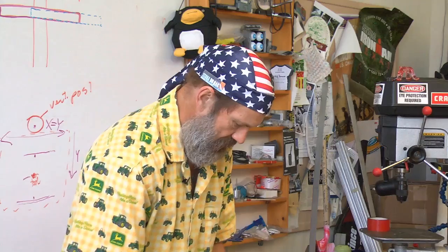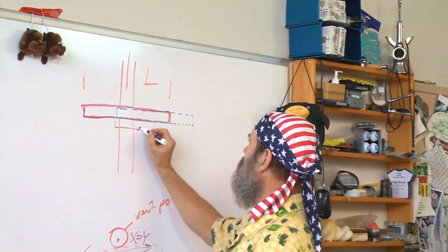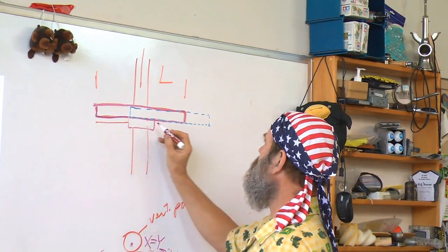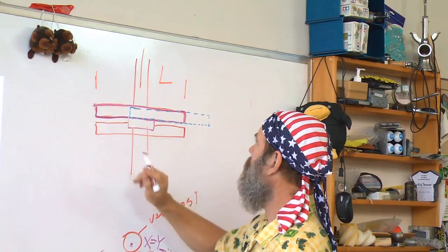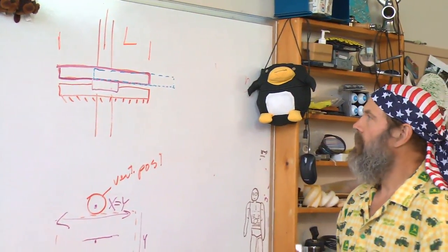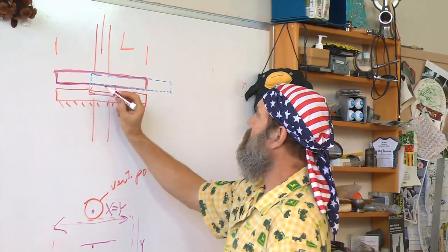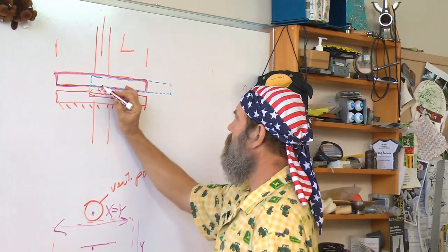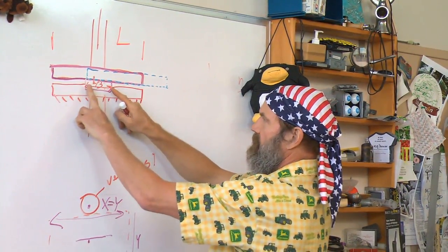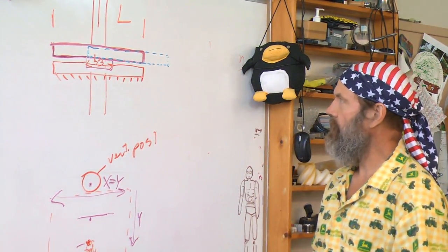If I were to do that, that would mean that, for example, I put a bearing block here and then a rail underneath it, where the rail is fixed to the column. Saint-Venant tells us if this is L, that this bearing engagement better be at least L over 3. If this table gets much bigger than the spacing on the bearing blocks, then it's going to be too soft. What else do we notice?